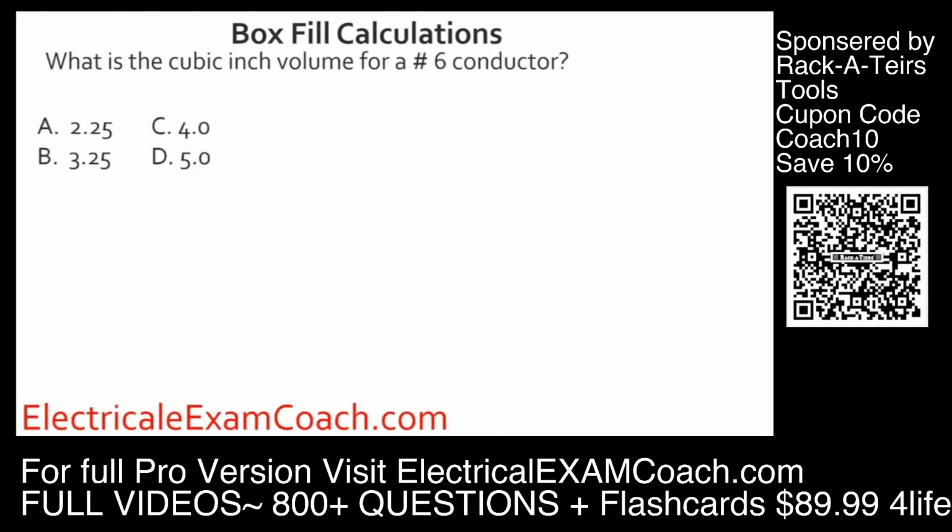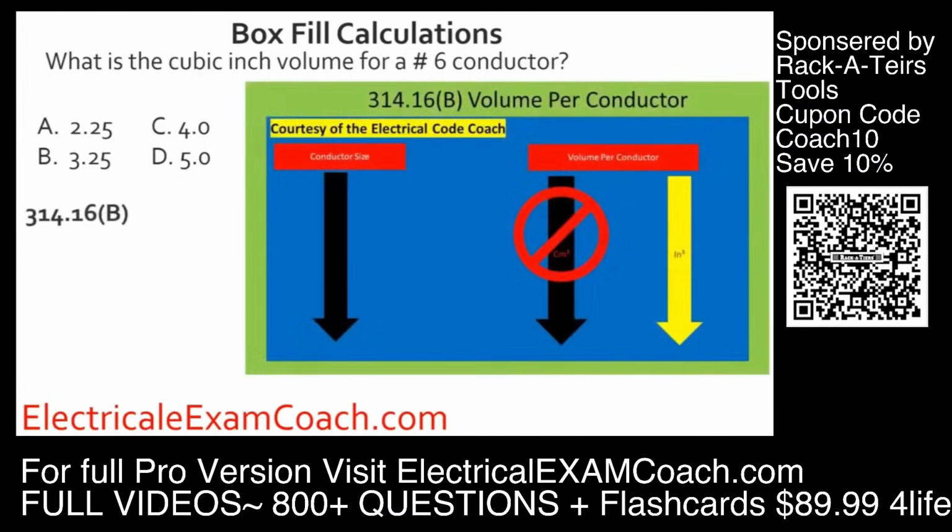What is the cubic inch volume for a number 6 conductor? For this one, we're going to head to 314.16(B). We're going to start here on the left-hand side of the table and find our size conductor. Then we're going to cross over to our cubic inch volume, and we're going to select D. Great job!